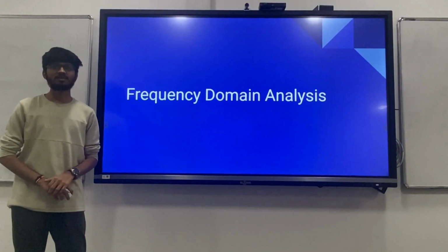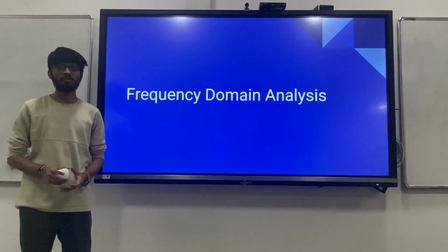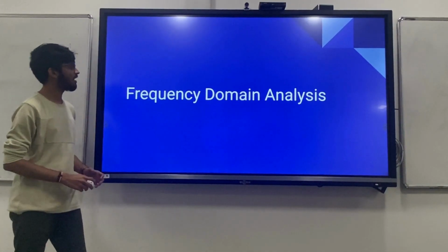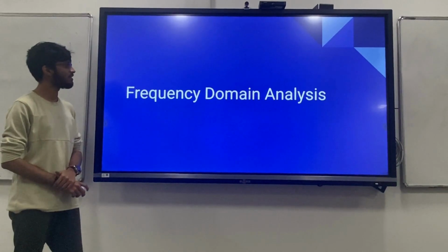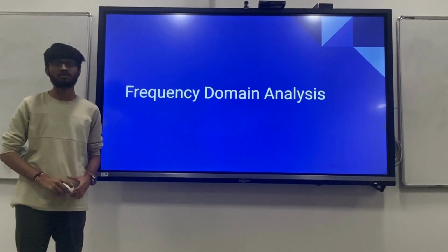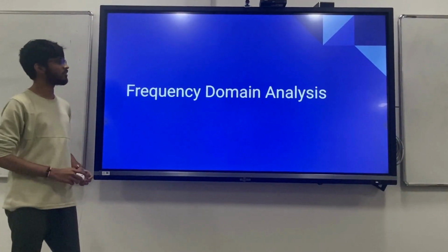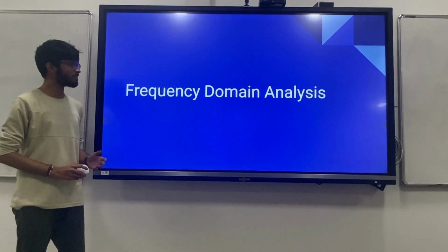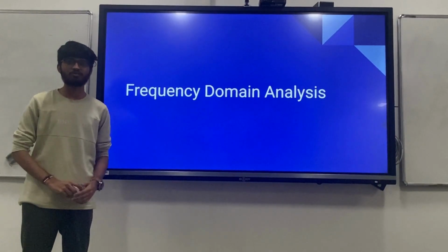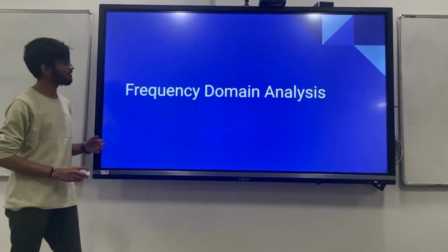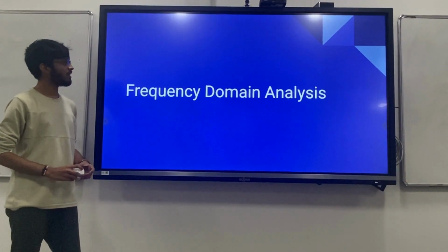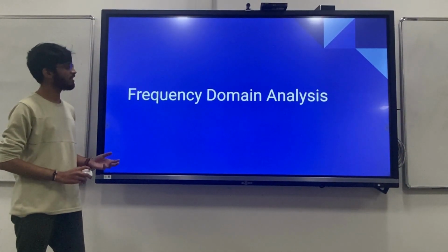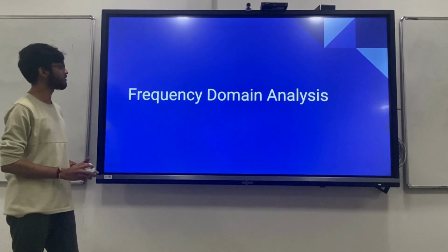After performing data processing in the form of notch filter and band pass filter, and obtaining the required signal, we analyzed the signal in the time domain and observed the mean absolute value and the root mean square value of the signal. After that, the next obvious step would be to analyze the signal in the frequency domain, which could provide us with a lot of useful information, and perform some analysis and some variations to the signal in the frequency domain.